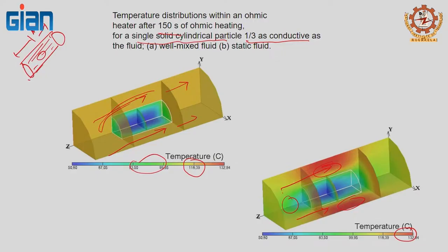So, in other words, you have to understand how well the electrical conductivity in the liquid and solid is matched, so that for the current it looks like the same mass, whether it is a liquid or solid. If it is the same electrical conductivity, it is going to heat much more uniformly, whereas when the values are different, then they are going to have different temperature distribution.